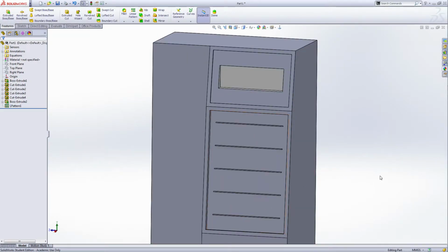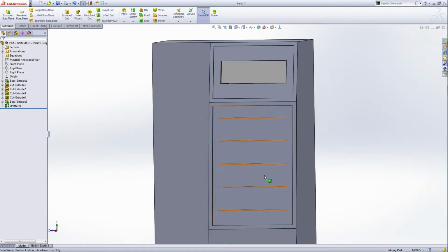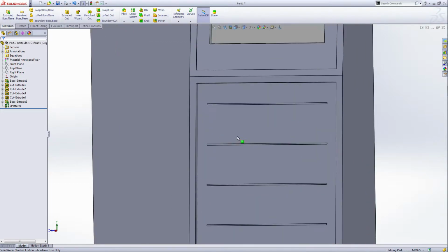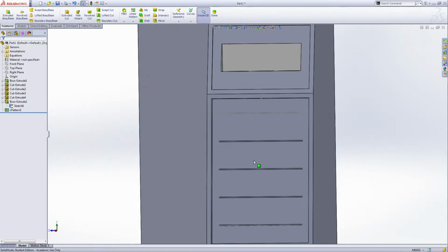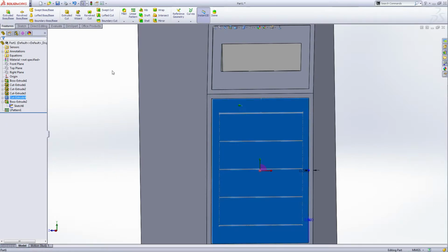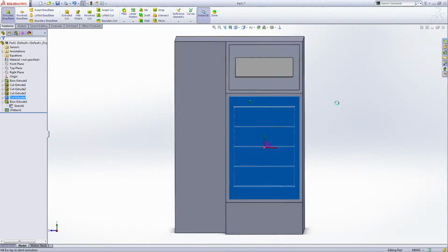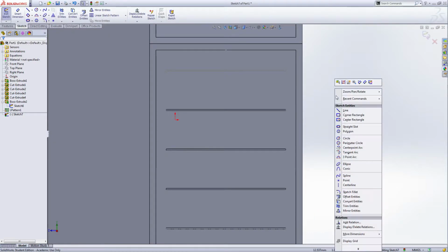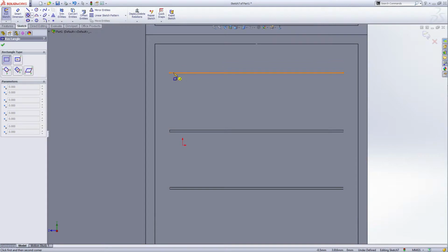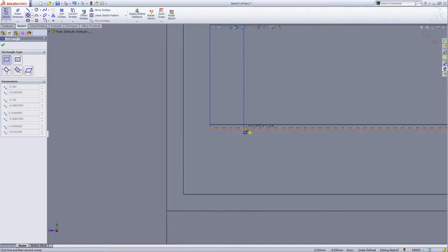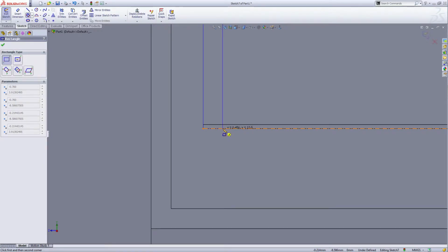Okay, see, we got the 5 of the frames, and now we're gonna add more of them. So click here, and this sketch, show this sketch, because we're gonna use this frame, use the reference frame we made, and select this face again, and then make another extrude base. Okay. Now we select the corner rectangle again. So you still can see the reference frame we made before. So select this point again, draw another rectangle, and down to the bottom to this construction rectangle.